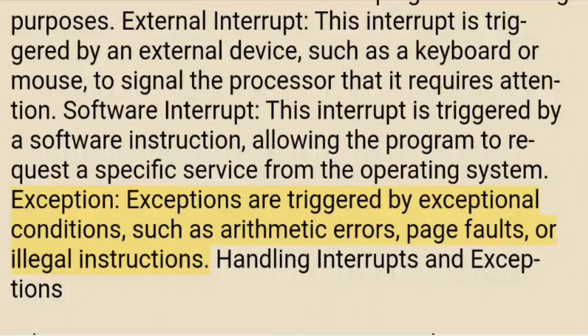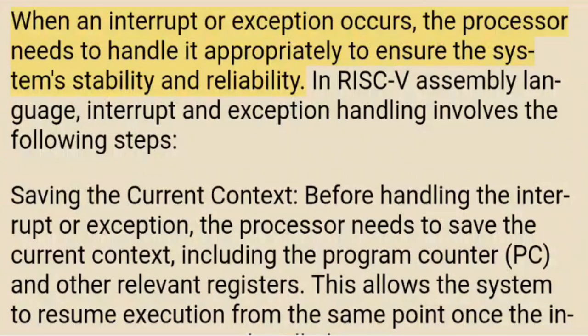Exceptions are triggered by exceptional conditions, such as arithmetic errors, page faults, or illegal instructions. Handling interrupts and exceptions. When an interrupt or exception occurs, the processor needs to handle it appropriately to ensure the system's stability and reliability. In RISC-V assembly language, interrupt and exception handling involves the following steps.